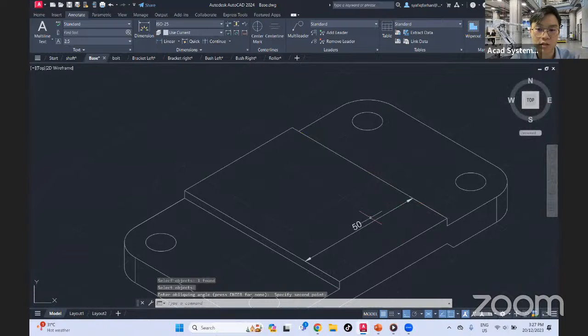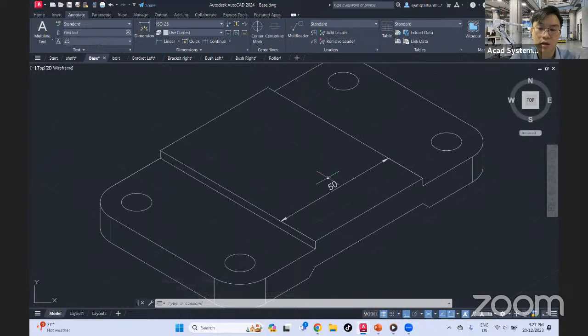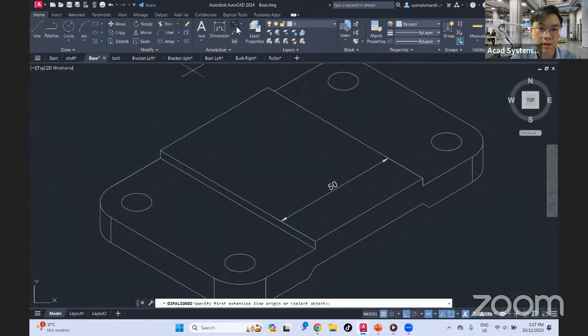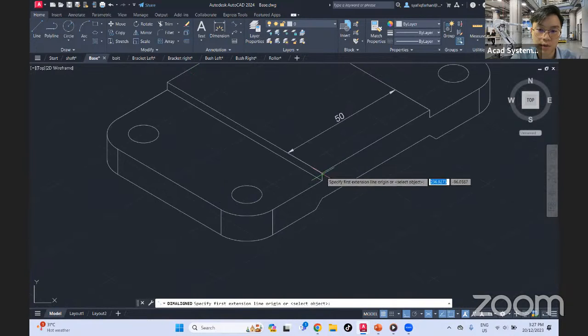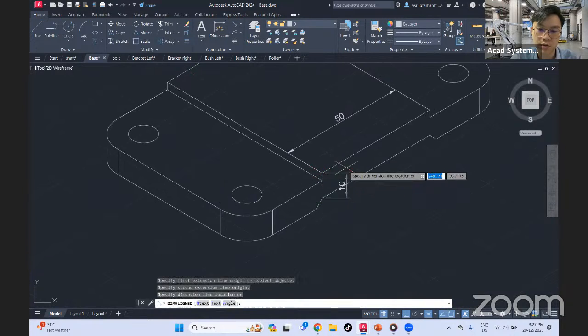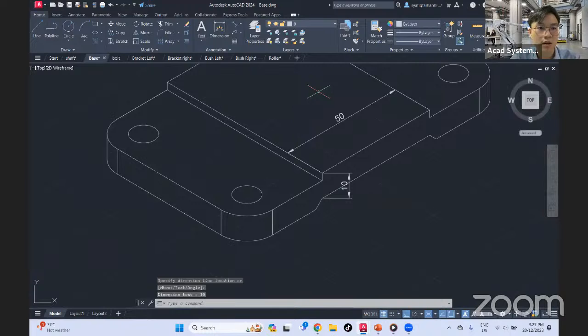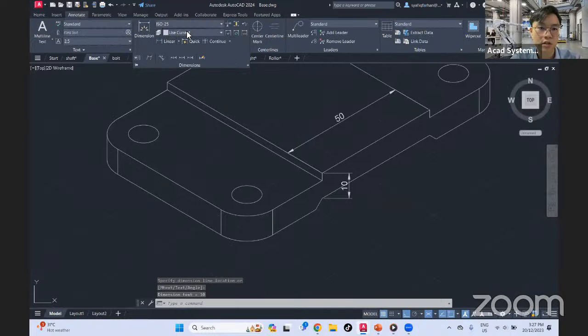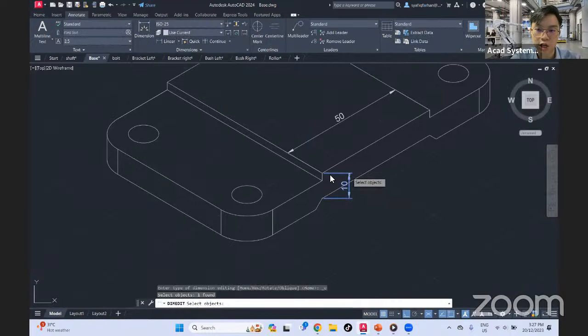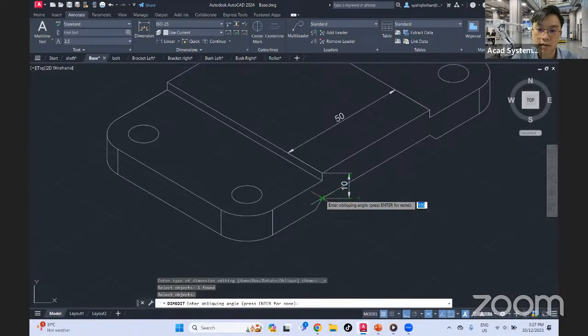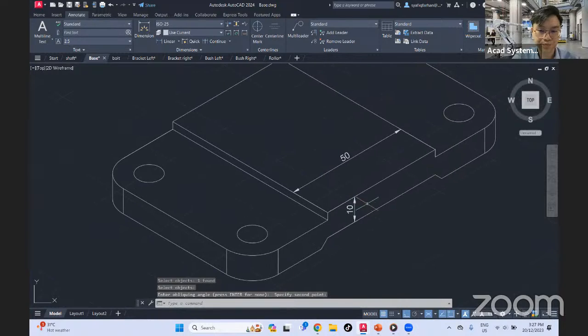So you snap and align with the flat of the drawings. So if I repeat, align over here, probably I want to measure from here to here, it's 10. And go back into dimension here, oblique, select object, enter, oblique angle, select one base point and snap along it.